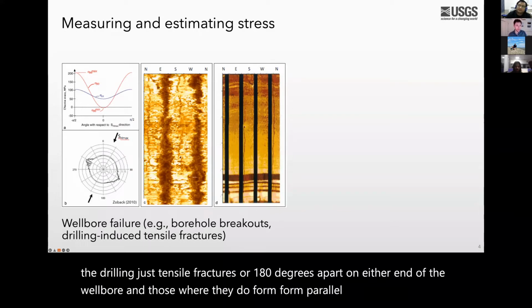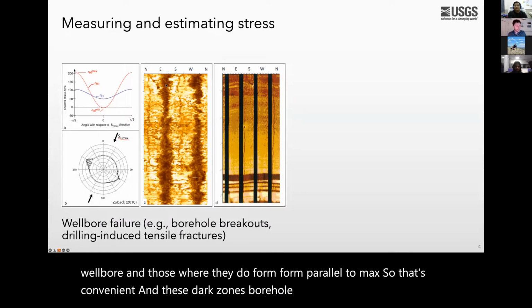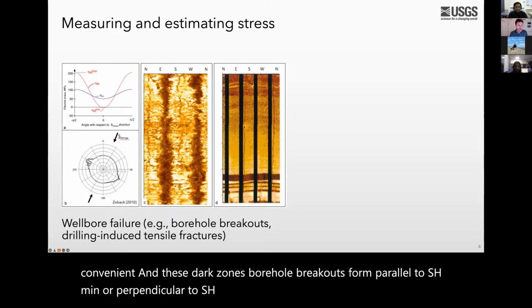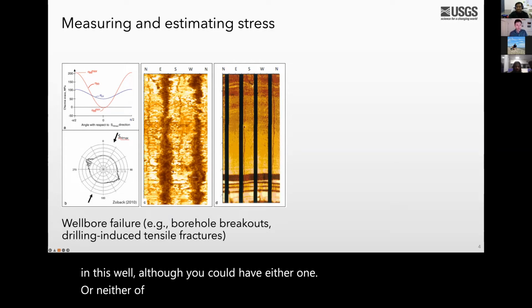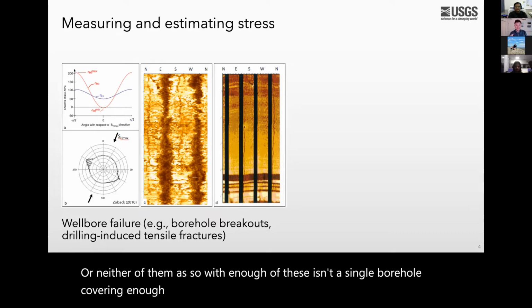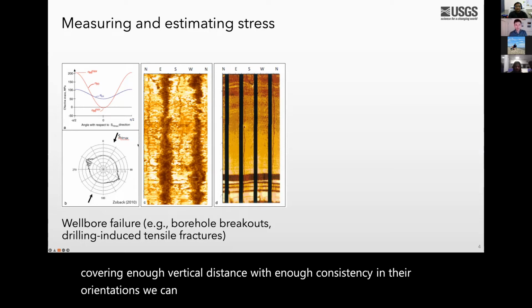So that's convenient. And these dark zones, borehole breakouts, form parallel to SH min or perpendicular to SH max. It just so happens that both are present in this well, although you could have either one or neither of them as well. So with enough of these in a single borehole covering enough vertical distance, with enough consistency in their orientations, we can obtain a reliable measurement of SH max orientation.